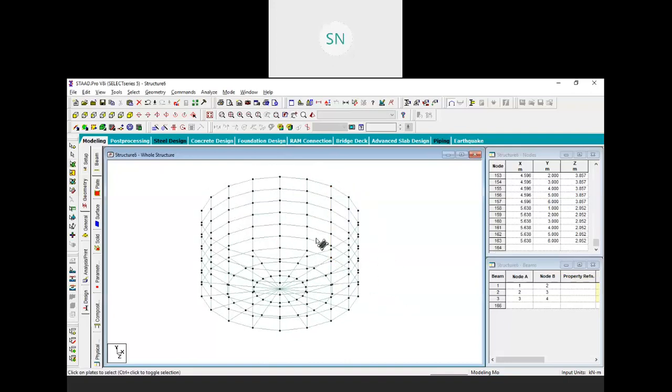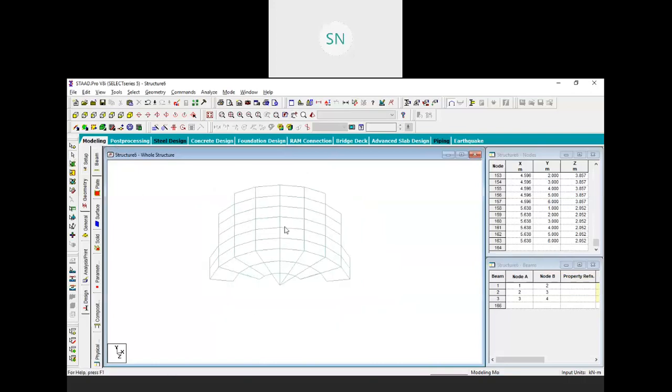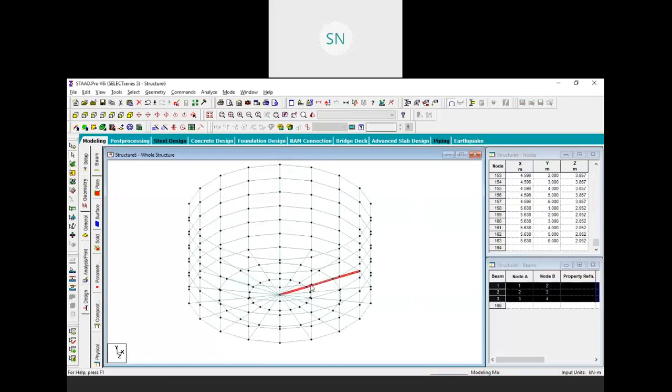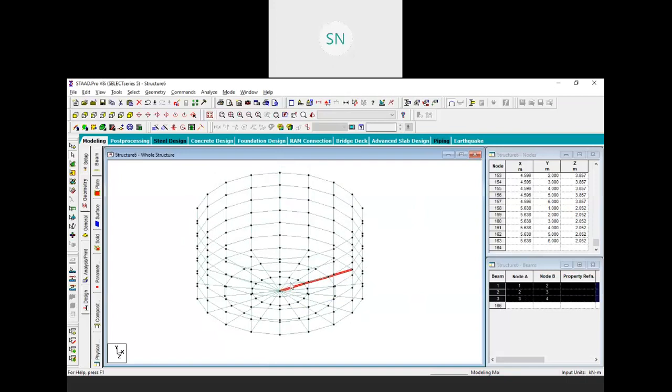Now we are going to design our support structure. For that, initially we create 3 beams over here, right? You will get that thing with the beam cursor. Select beam cursor, select your model, all the beams will be selected. So these are the beams. So what I am doing is a circular pattern of these beams. I want 6 copies for the support. This is our beam. These are the plates, right?